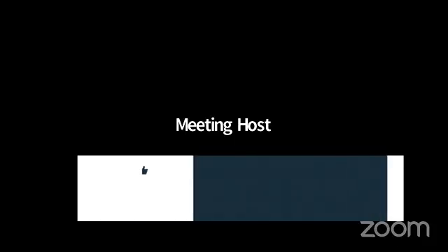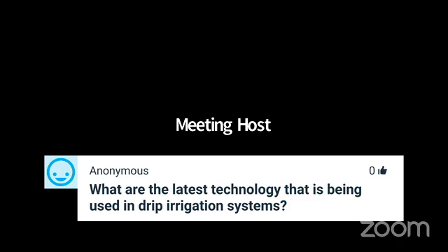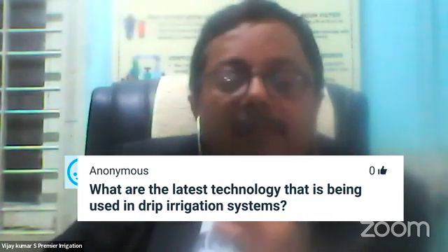Okay. What are the latest technologies being used in drip irrigation systems? Yeah, today this is a very good question. In fact, today it has become totally digital. But it is again a question of affordability. If the farmer or the corporate is able to afford these systems, you can go in for automated systems where you have either a timer-based, volume-based or real-time-based system. That is one available. And now even later systems, like people are using remote sensing and indices like NDVI, wherein you can exactly know the moisture status of the soil and do real-time irrigation.